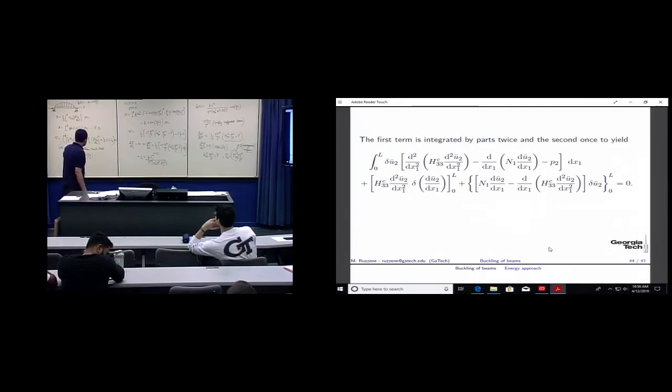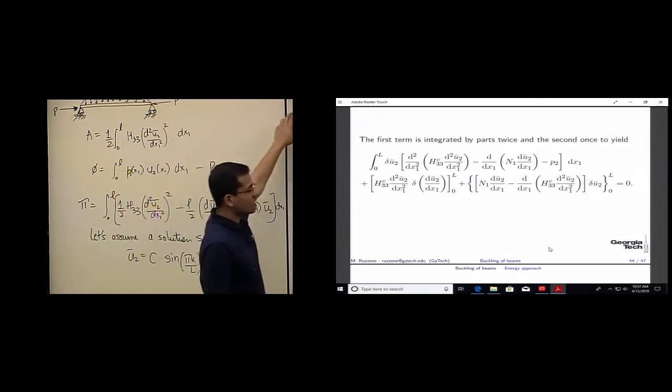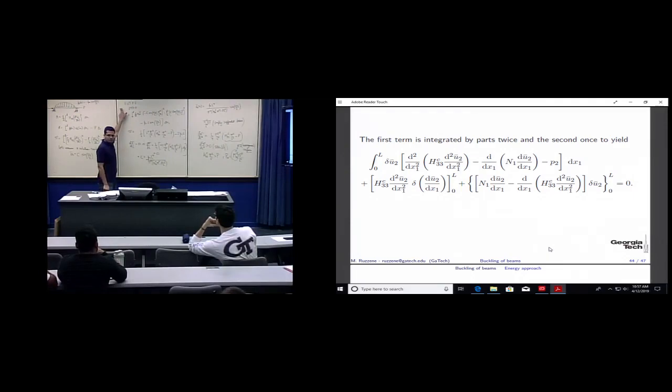So we used an assumed solution which took the shape of the exact solution, found the constant using the principle of stationary total potential energy, calculated the unknown, and finally we used the principle of minimum total potential energy to find the character of the system.